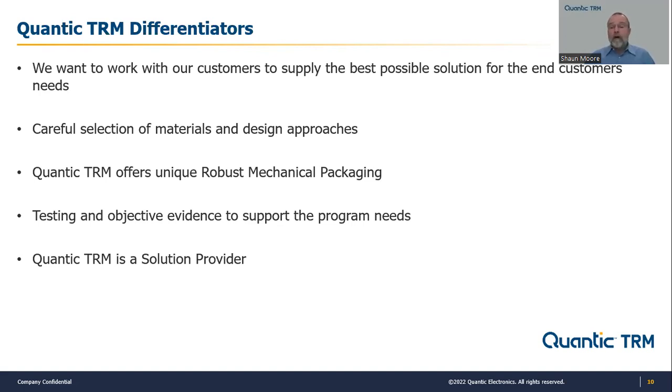Some people will go in there and offer, for example, if I can get more bandwidth, it must be better. Well, more bandwidth usually comes at a cost, and it's usually insertion loss or reduced isolation or reduced amplitude tracking or any other parameter.